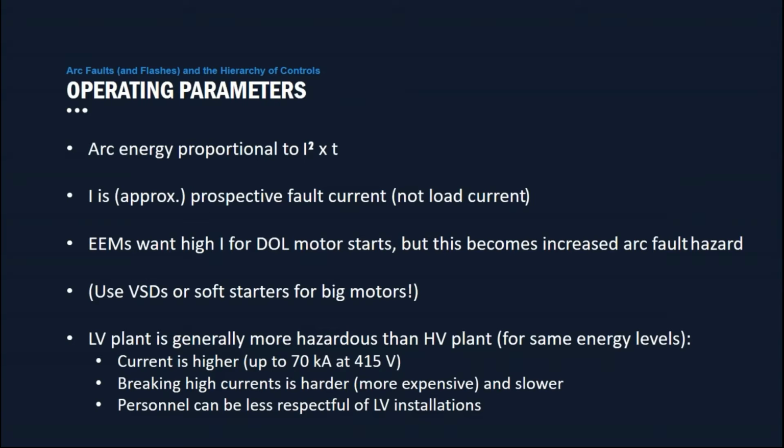The energy in an arc is proportional to I squared times time. And the I in this case is the prospective fault current. It's not your load current. So don't confuse the two. Most engineers listening on this call will understand that the fault current can be way different.